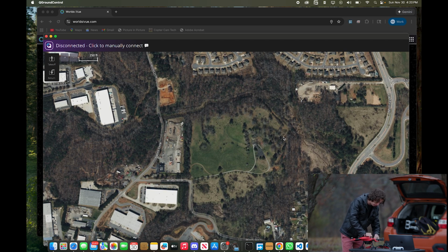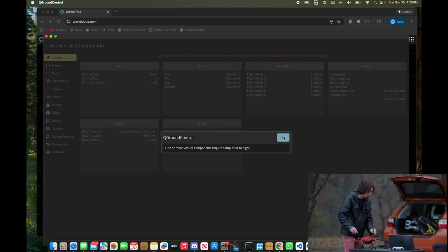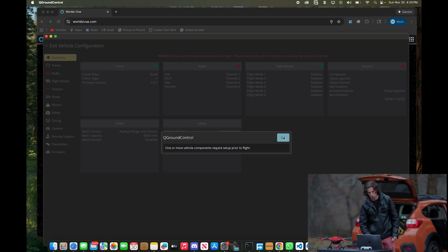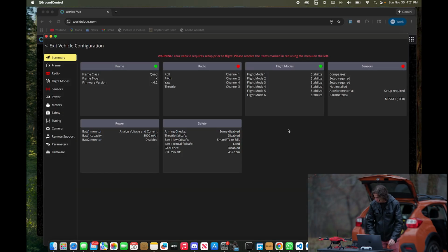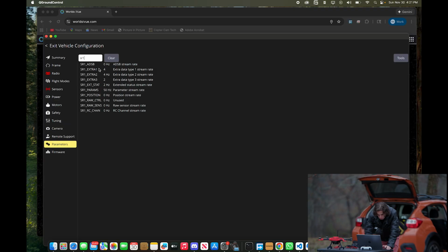There's a couple layers of heat shrink that go around the USB-C cable, or the female connector of the USB-C cable, and sometimes the tolerance is such that you can just mechanically fit it in there. Other times we actually need to cut off one of the layers of heat shrink and then glue, using some CA glue, to hold that USB-C extension cable in there. All right, but back to reality, or the parameters.